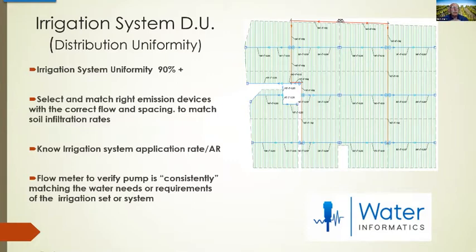So what happens is you'll turn that pump on, and if you're getting 600 gallons to start, in 12 hours, it might go down to 550. In 12 to 24 hours, we may see it go down to 500. In a 48-hour run, it may go to 450.